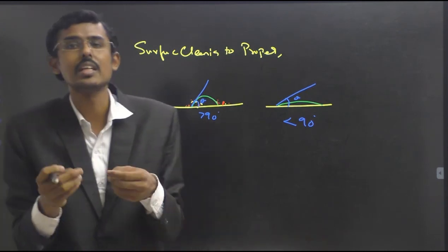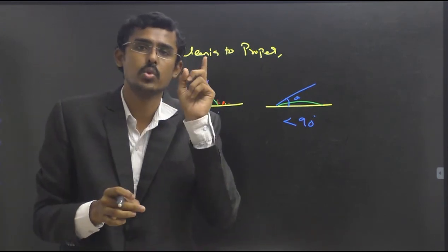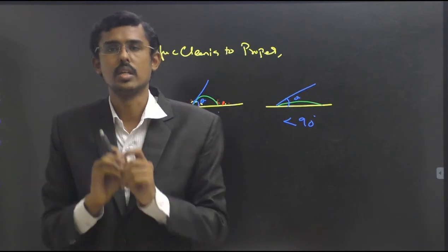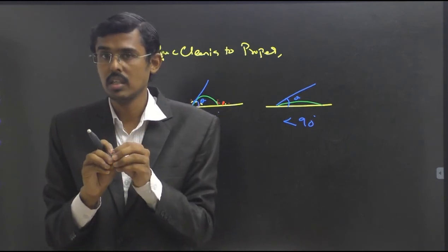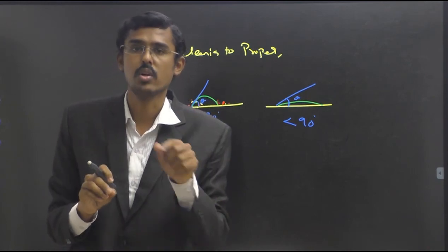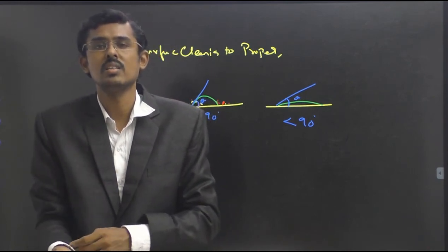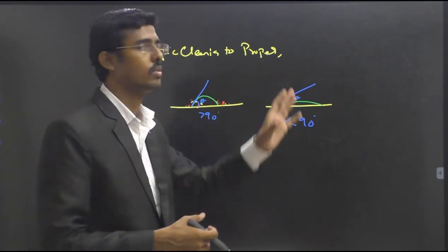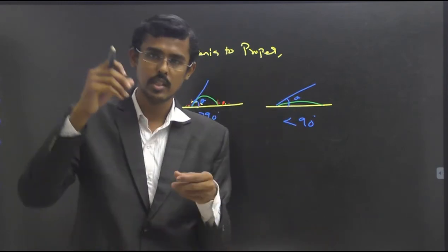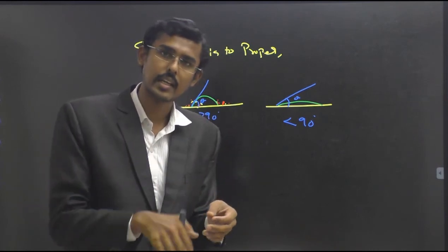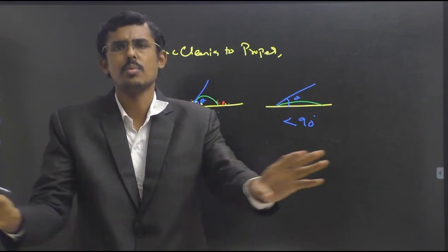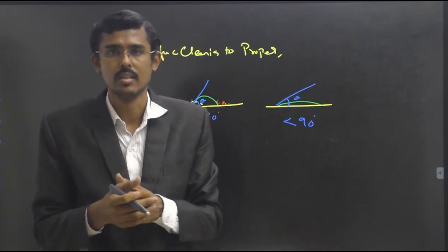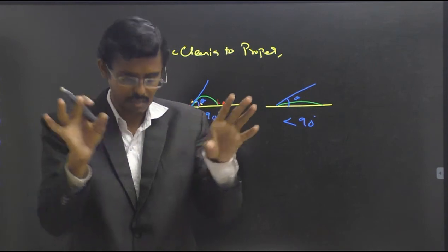It means the surface cleaning is most important. We have studied in the procedure the pre-cleaning process, and then application of the penetrant. Even for the application of penetrant, pre-cleaning is most important. If you have not done this pre-cleaning process, the contact angle will not come, therefore wettability will not be there, therefore flow of the liquid into the crack areas will not be there. So this stops the process. We won't get the accuracy of results we want. It will end in error.